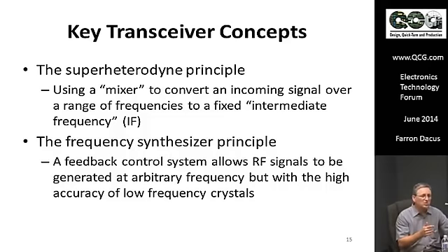First off, it converts the incoming signal to a fixed frequency where you can use an extremely good filter, a ceramic filter or a crystal filter historically, though these days it's often a low IF filter on die or digital signal filtering. But in addition to it being some type of physical process that allows narrow bandwidth because it's fixed, it's also converted down to a lower frequency. And at a lower frequency, for any given Q, the bandwidth is proportional to frequency. And so that lets you get that bandwidth down.